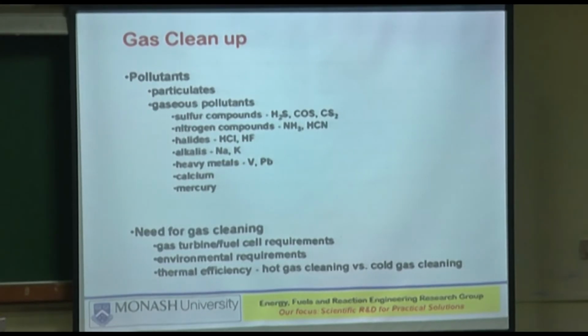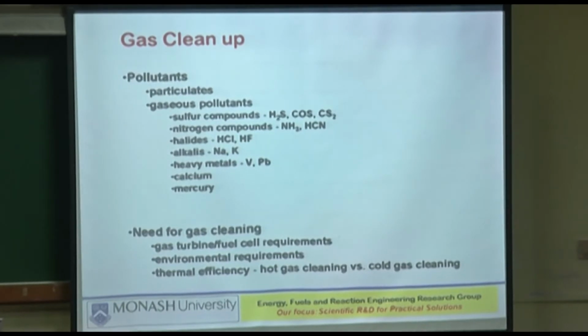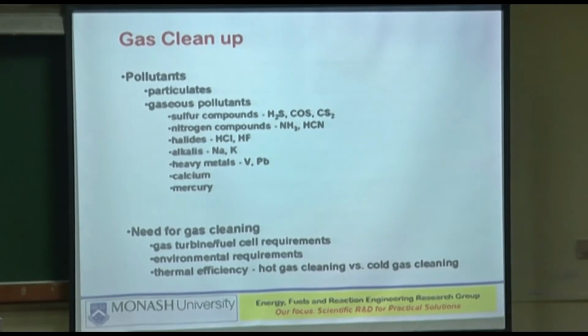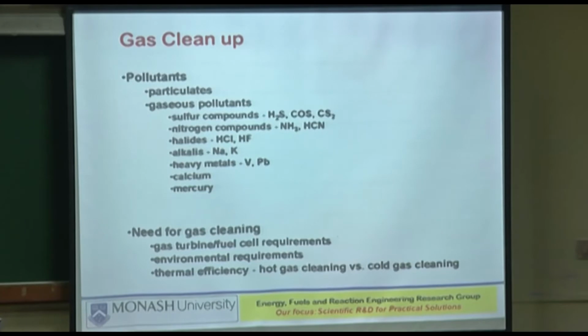Hot gas cleaning obviously avoids the exergetic losses, but it's easier said than done, because even now hot gas cleanup is not fully developed, and especially at 800, 900 degrees centigrade it is still a major challenge. There is a lot of US Department of Energy funded work on hot gas cleanup that went on in the mid-90s when our PFBC was still in vogue.